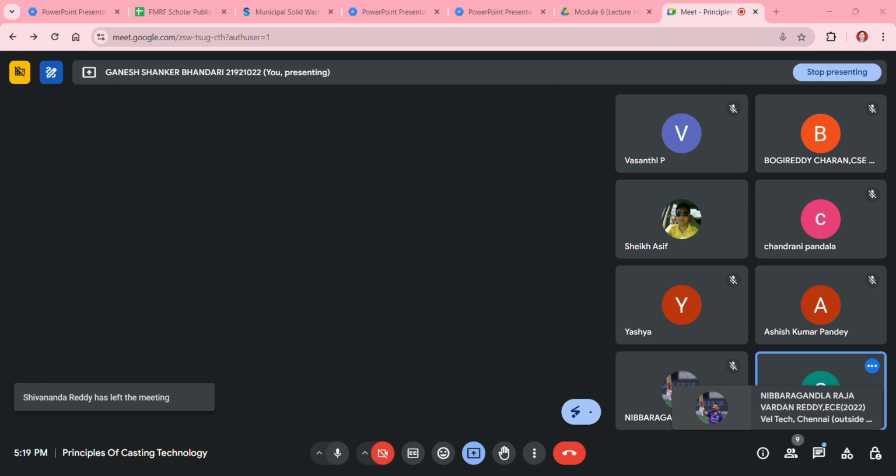So we have this data. What data do we have? We have container unloading time around 0.05 hours per container, and the haul time constants are A equal to 0.022 hour per trip and B equal to 0.14 hour per kilometer, and the at-site time is this. So what was the pickup time?